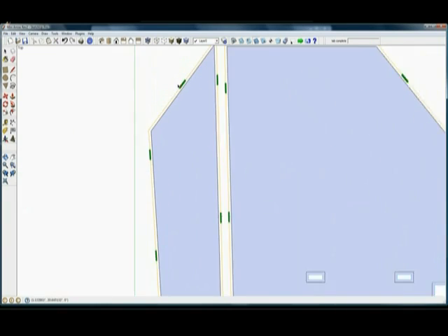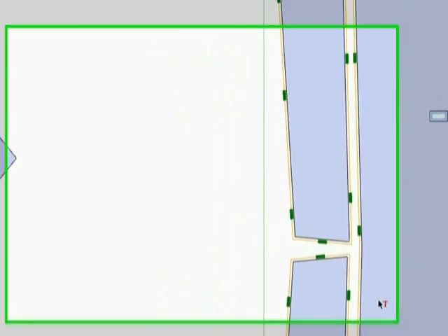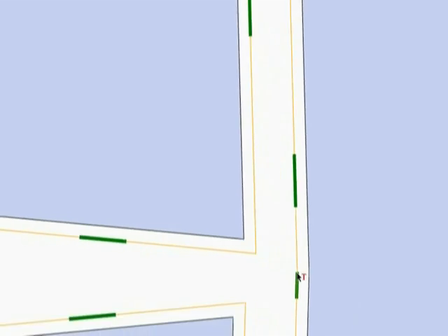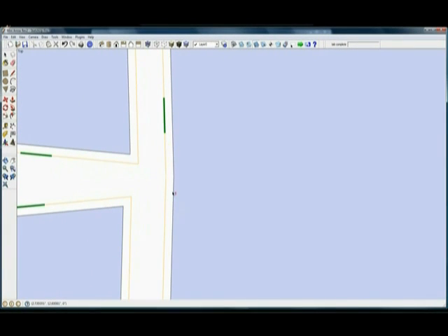Sometimes on some parts, I think I saw one over here, you're going to find that your tab tool is not going to give you a full width tab. That happens a lot on arcs. For instance, we know we have a 1/4 inch wide tab width, and this is demonstrating that. But when I come over here, if I wanted to put a tab there, I see that tab is not as long as the other one.